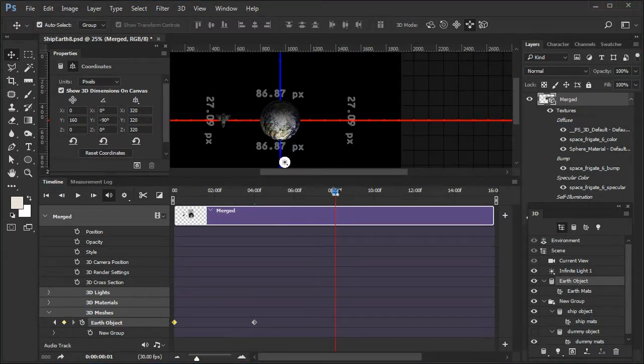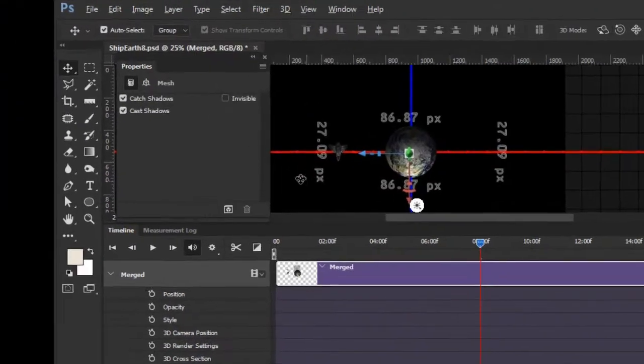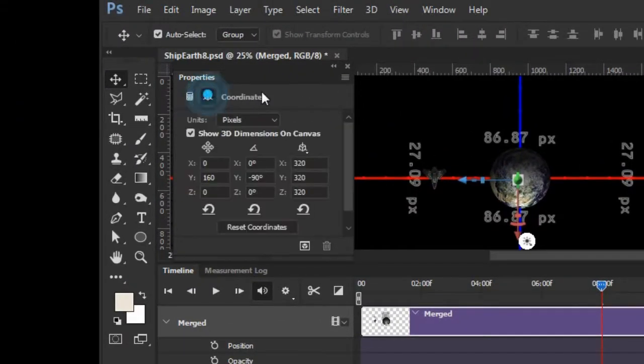Now drag the playhead to the 8-second position. Then choose the coordinates again in the Properties panel. Change all degrees in the degrees column to 0. Then change them to -180, 0, and -180. If you end up with +180, 0, +180, that's okay too.